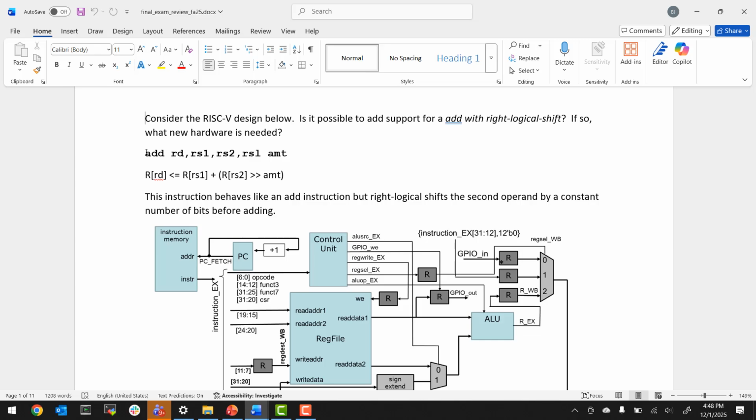But then if you want to accumulate that, and add that value to a sum that has 4 fractional bits, you can't add a number with 4 fractional bits to a number with 8 fractional bits. You have to line up the decimal points first, making the number of fractional bits consistent before you add or subtract.